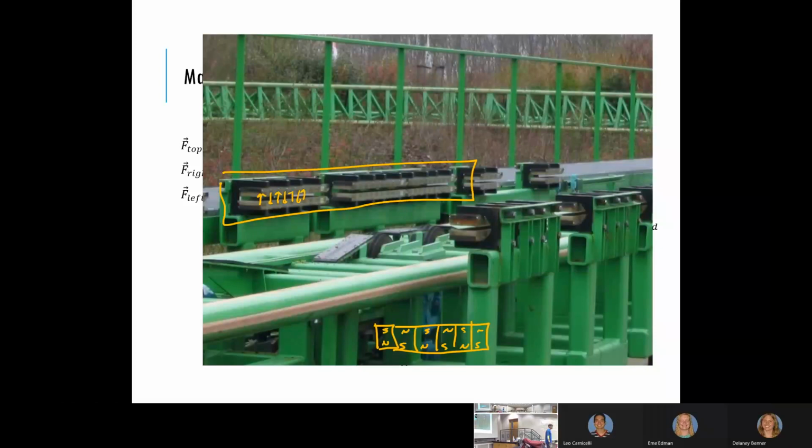You're done. No moving parts required. Well, okay, the roller coaster cart's moving, but it's not like brake pads pressing up against something on the cart. The roller coaster just goes through this magnetic field, those little fins on the side, and that automatically slows the cart down. And of course, you've got a series of them all the way through.